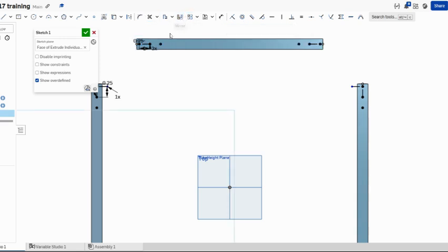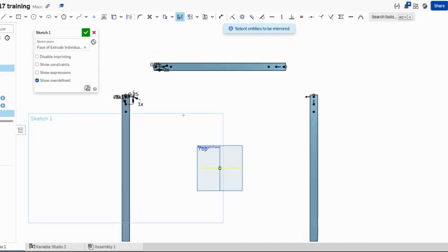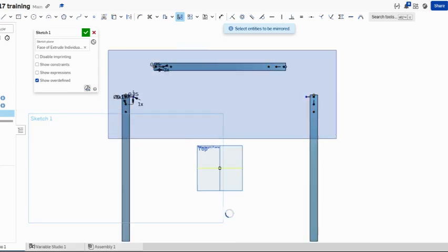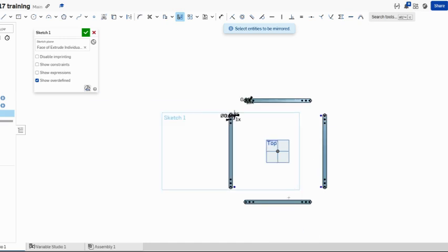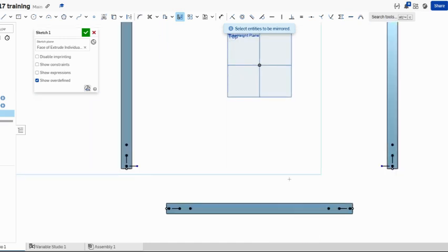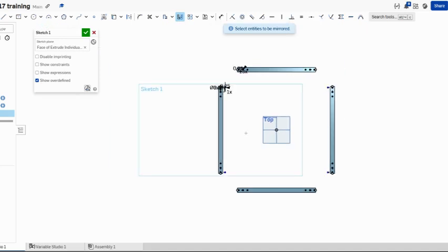And you'll notice I'm not doing holes everywhere. We used to do that. We're trying to really reduce that. Now we're trying to just do the holes that we need. Two things. Number one, it really reduces our machining time. And we'll call that sketch top holes.